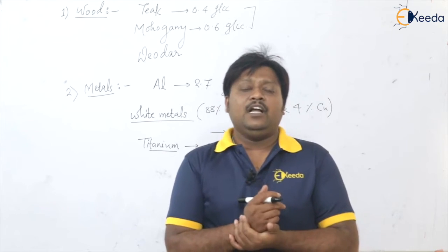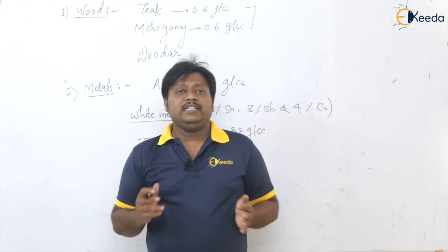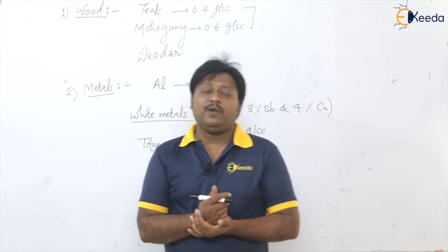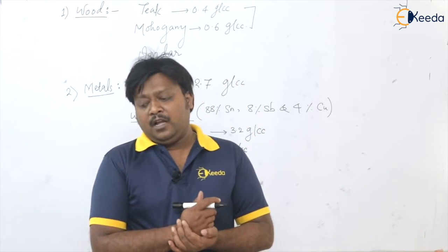Only thing is that whenever your pattern is made of metal, we have to provide double the shrinkage allowance on the master pattern, which is made of wood.